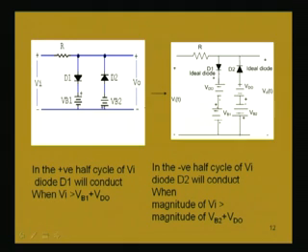So, the negative half of the input cycle will be such that whenever this point's potential is higher than this potential, which is VB2 plus VD naught, but with a negative sign, because we are considering the negative half cycle. So, the magnitude of this Vi must be higher than the magnitude of this total voltage in the negative half cycle we are considering.